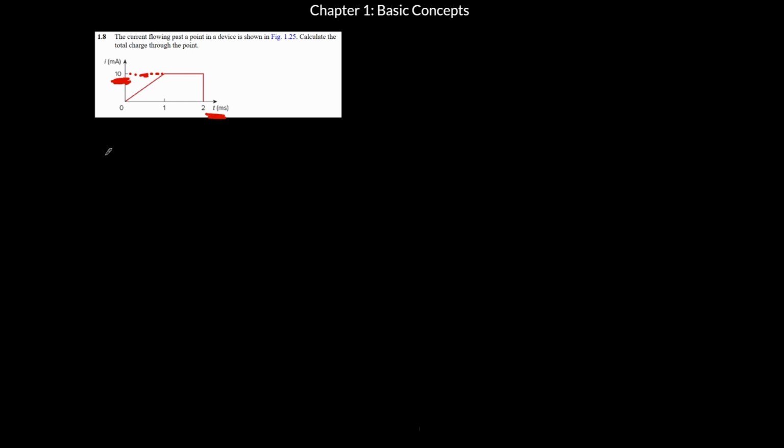And you know, we could take the integral of the i to get our charge, right? But we can do this without taking any integrals, really. And that is basically just splitting this graph up into 2 parts. So from 0 to 1 right here, so our time there, we're just going to have this 10. So this 10 times our 1 for our 1 second.